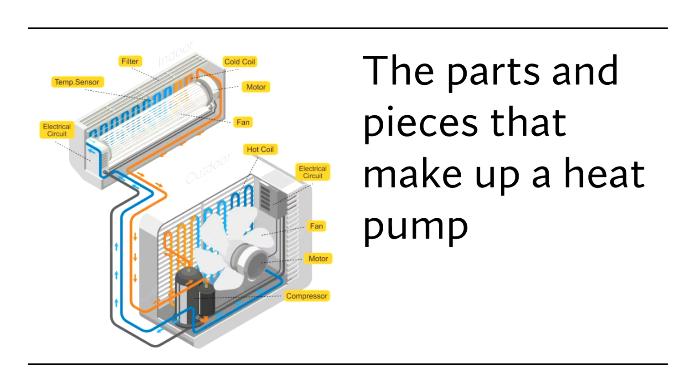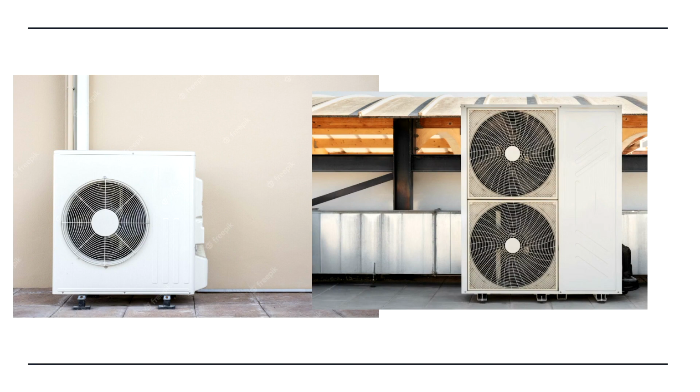Now, the head, there's a couple different options, and we'll talk about those here in a few minutes. And the outdoor unit is usually what's called a slim condensing coil unit. And by that I mean they're only about 18 inches deep. They're usually, depending on the size of the capacity of these things, anywhere from about 40 inches wide to about 3 feet high, so 36 inches. Okay, they do get bigger, and I'll show you some pictures of those coming up right here.